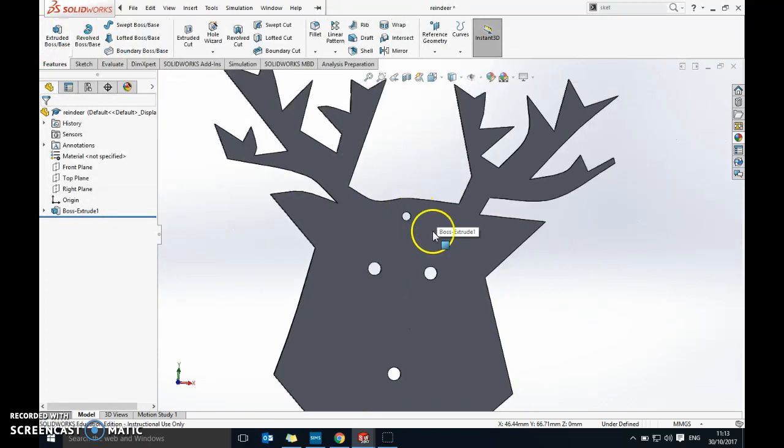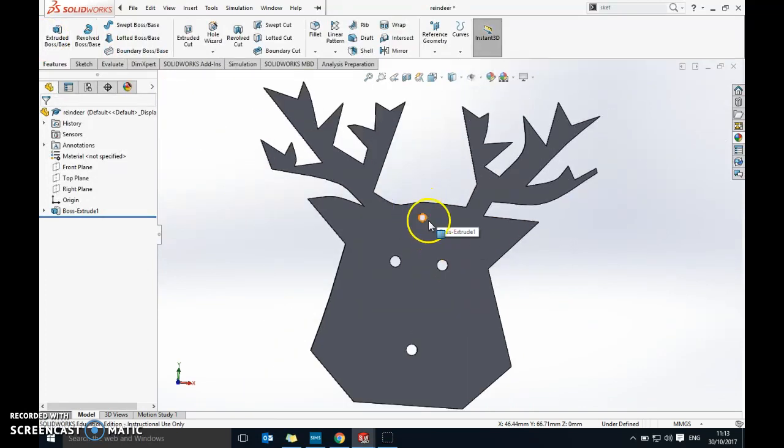Alright. Ideally, you don't want it to be any closer than maybe about 3 mil, because that's the thickness of the material. You don't want to make an extra weak part. Okay, so I've now got my hole there. That's going to have the wire going through. I've checked that the mating works with these, and the board fits nicely on the back behind there.